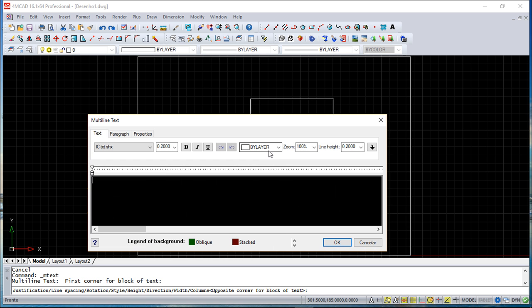One second please. So the format, it is the size of the vector, then this sign, angle from the x and y plane separated by a comma, and then you put, for example, a value which is the z coordinate from the x and y plane to the z level where you want to place that point. Okay, these are the cylindrical coordinates.